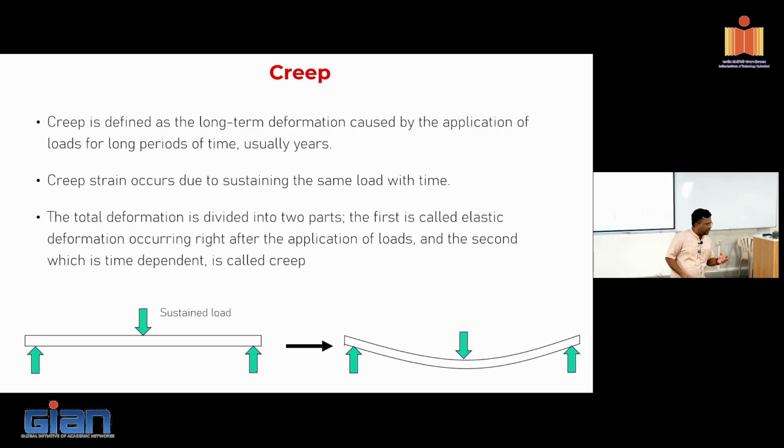But if you're not careful about creep, if your material has a lot of cementitious system, they undergo creep more. And if you have a lot of unutilized water, then they creep more. In fact, by putting more coarse aggregate, you can reduce the creep significantly. But in UHPC, we go the other way around. But still the creep deformations in UHPC will be less.